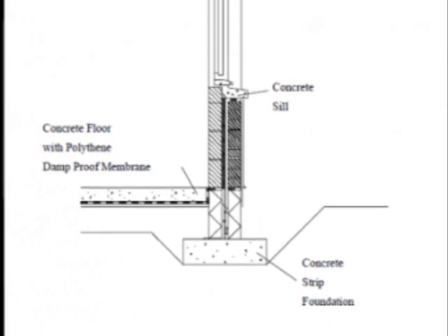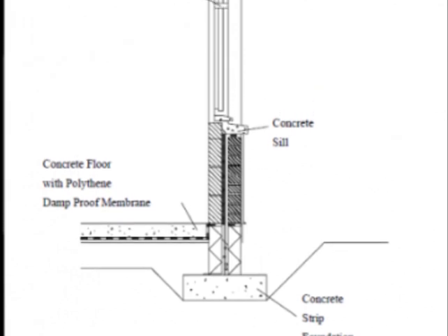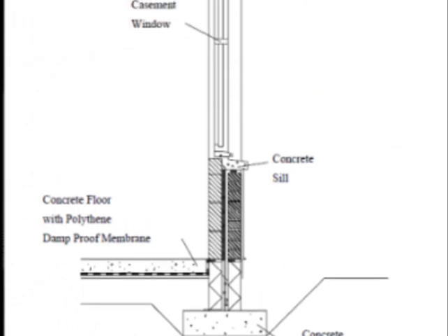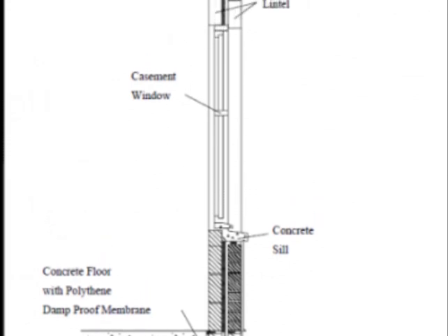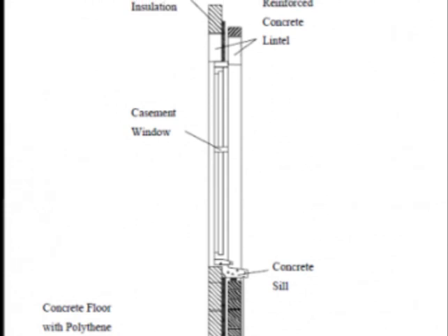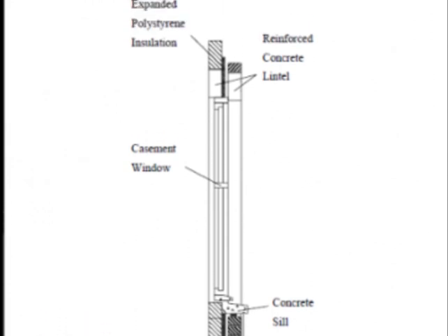Component drawings provide detailed information about individual units. They may be drawn at large scales such as 1 to 10, 1 to 5, 1 to 2, 1 to 1, and may include information such as component dimensions, construction, tolerances, and so on.